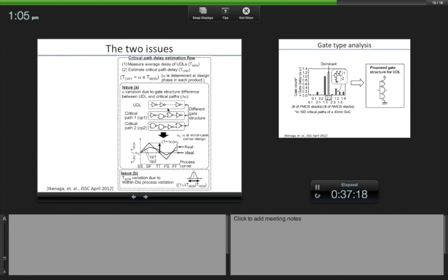and then what they do is they compare the delay of their universal delay line with the delay of the critical paths, and what they find is that across different process corners, so this is just a schematic to show, right? So say you have 2 different critical paths, schematically, conceptually, what should alpha be, right? So let us say if you look at the ratio of the critical path to the monitor, delay of the monitor.